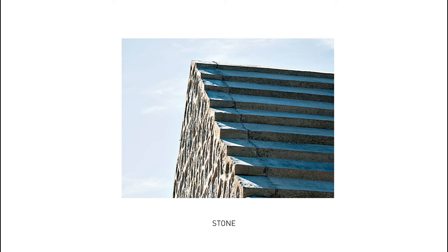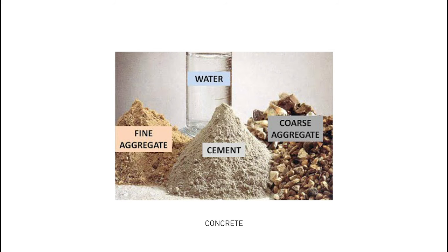Stone is one of the first materials chronologically when it comes to the method of massive construction. We distinguish between masonry stone and natural stone, where masonry stone is a ready-made form for building construction. The main components of masonry stones are lime, sand, clay, loam, and water. Concrete is a composite material composed of fine and coarse aggregate bonded together with a fluid cement that hardens over time. Many other non-cementitious types of concrete exist, with other methods of binding aggregate together, including asphalt concrete with a bitumen binder, which is frequently used for road surfaces, and polymer concrete that uses polymers as a binder.